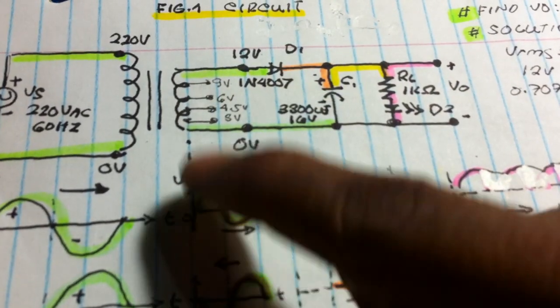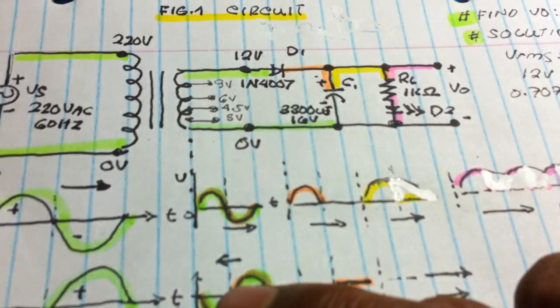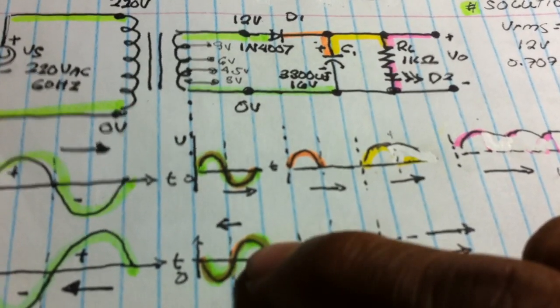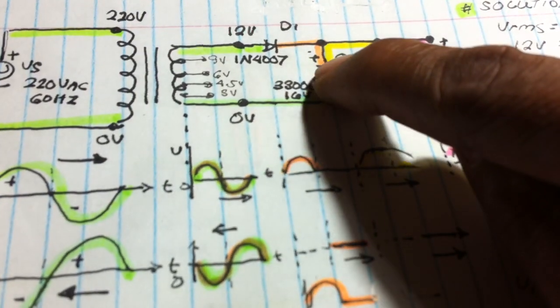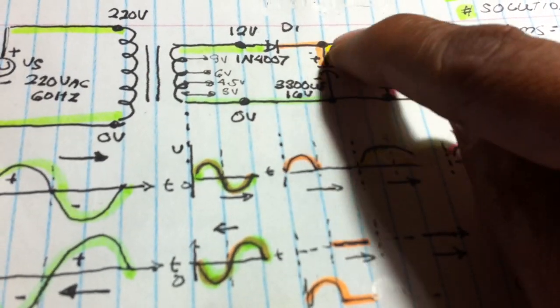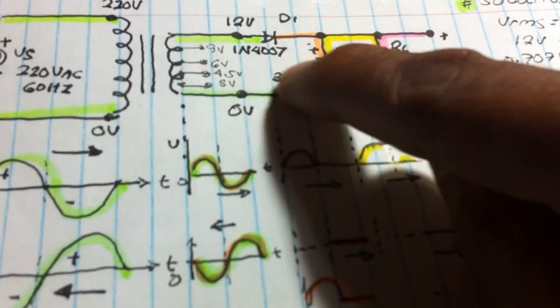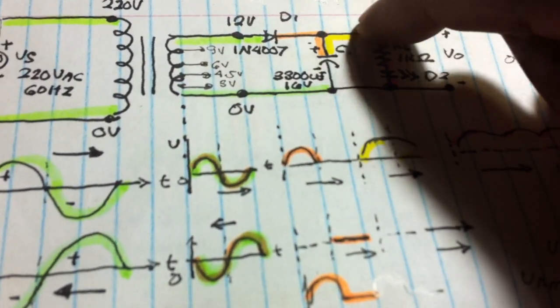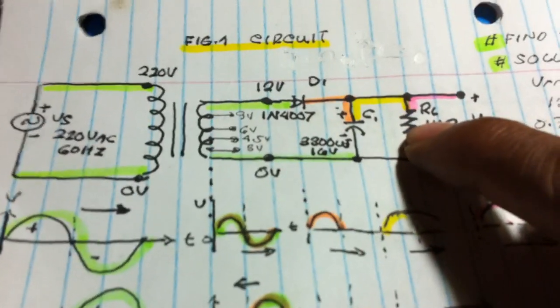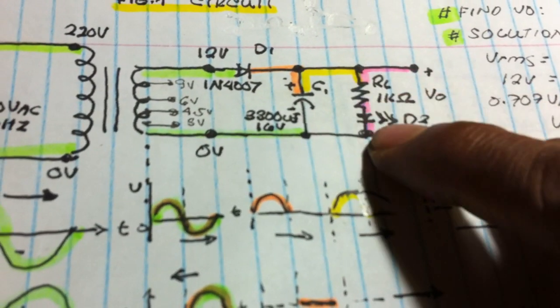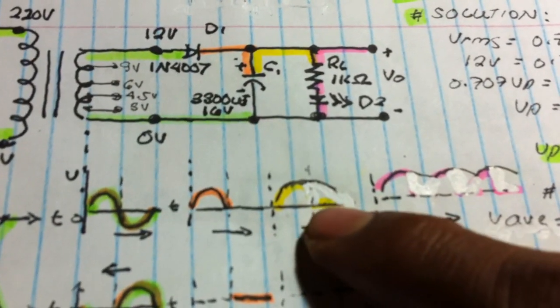So during the positive cycle, it charges the capacitor, and during the reversal of the wave, still there is positive on the other end. It helps to push to discharge the capacitor. So it's happening at the same time. Charging, positive cycle, still there's a positive cycle, reversing direction. Equals to this node, it will help discharging the capacitor to the load. So this is now the output.